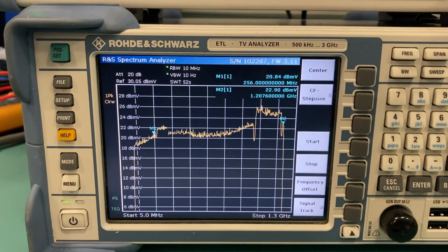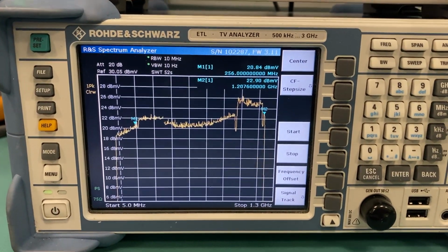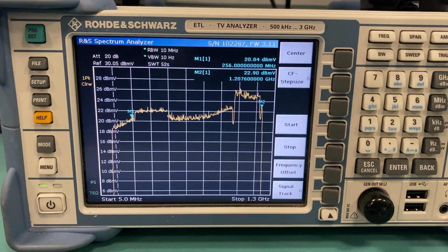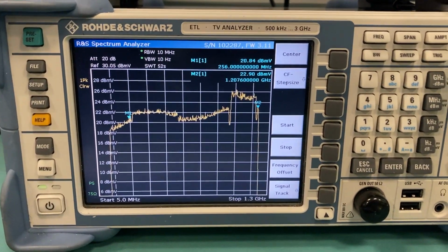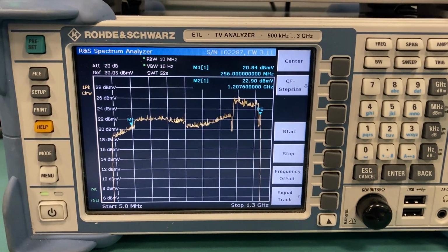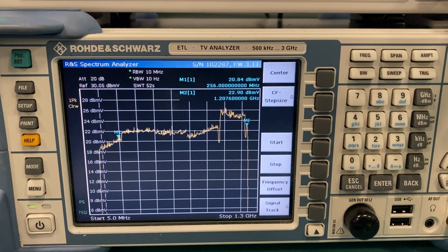And there we go. As I say, the analyzer's on a very slow response sweep time. So it takes a little while to update the screen. But yeah, that's basically increased the light level by 1 dB. So I'm actually going into the ONU at +1 at the moment.